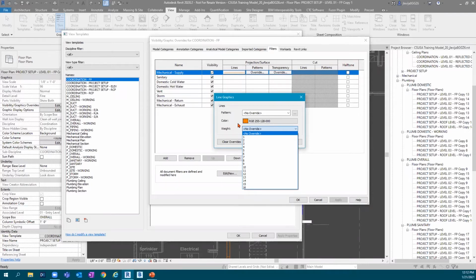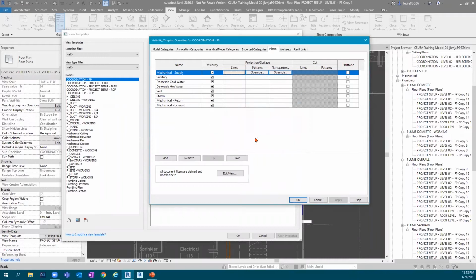You can take a look at the object styles, or you can go into that system and, within the type properties of that system, adjust this information further. That way you're doing a type scenario instead of an instance scenario. Those parameter things that we like to talk about on occasion.